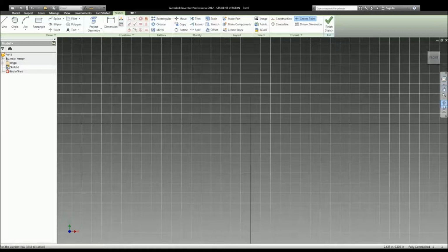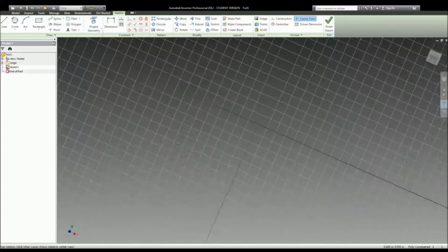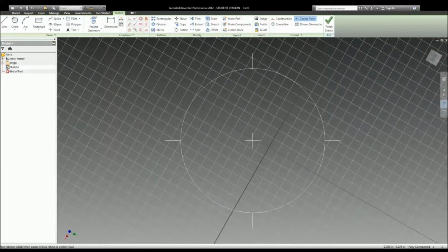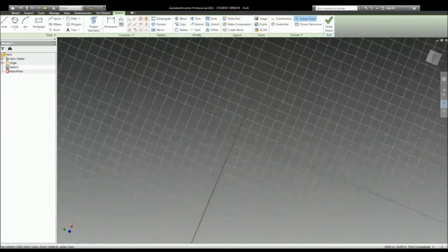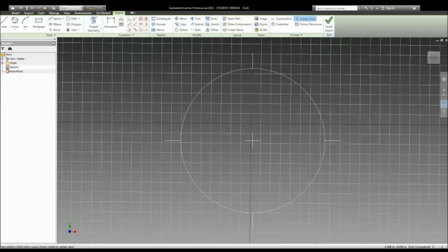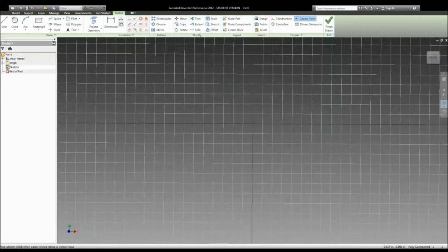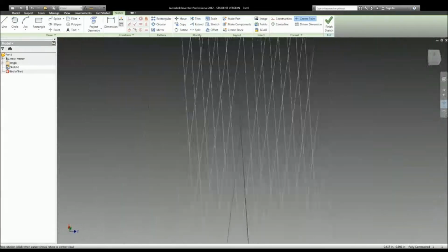I'm going to ignore the magnifying glass because it's just one of the zoom buttons, and I'm going to go to this one. This little crosshair that we have now is very similar to how this box works, but it kind of gives you hints as to what it does. The ring on the outside is for rotating your object or your drawing screen around this crosshair center, which is the center of your view. As you can see, it's rotating around that point. Now, if I click and drag inside the circle, I am orbiting around the object, like so.